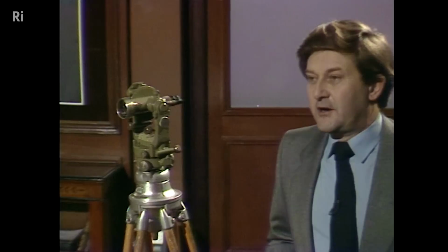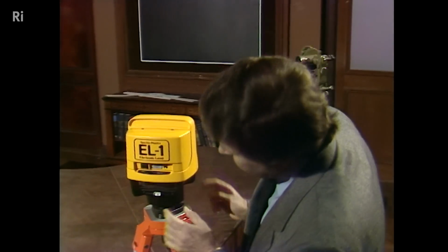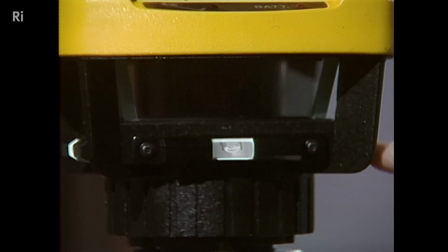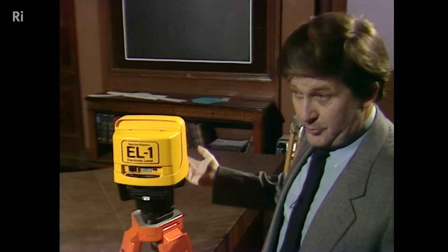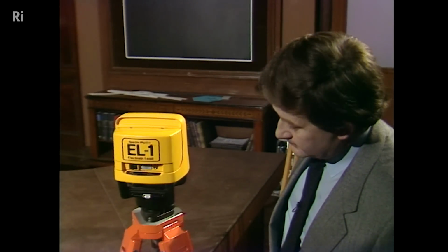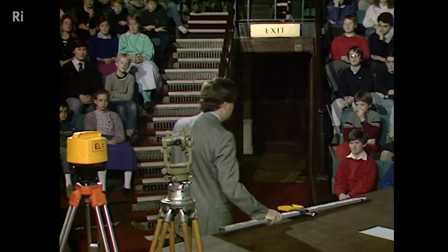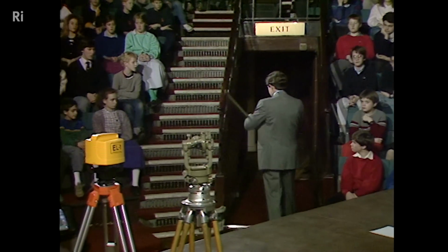How much better to have a machine of this sort? This is a laser leveler, and it has a little rotating diode infrared laser in there, which is now going round and round, spraying out a horizontal beam of quite safe infrared radiation into the room. Well, into the building site, as we're simulating. So now, having set this up, I'm the skilled man, I can now take this pole and go to the point that I want to measure. Should get it the right way up.